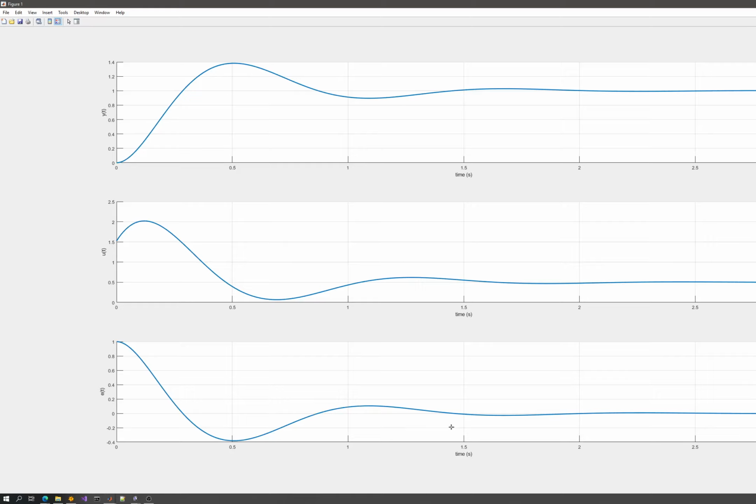So basically I'm trying to settle down, but I'm applying a little bit too much in terms of control signal, because if I would have stopped somewhere here, I might have ended up stopping at the right position, but that's depending on the control parameters that you use. Because you have a PI controller, you have an integral part and a proportional part, so this means that if I would have had a P-type controller, these two graphics should have been in the same shape.